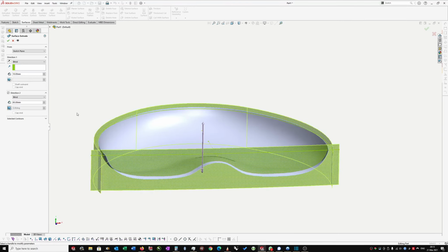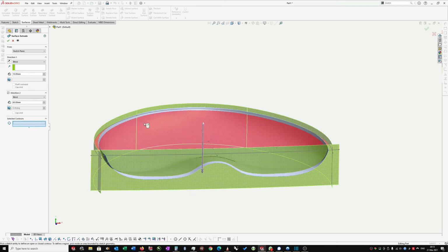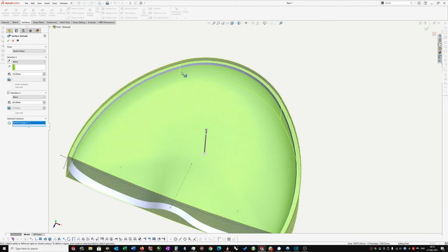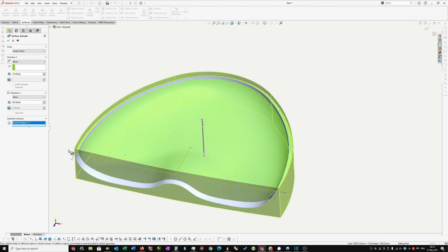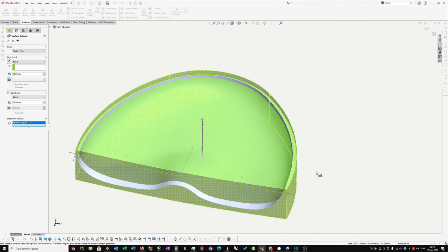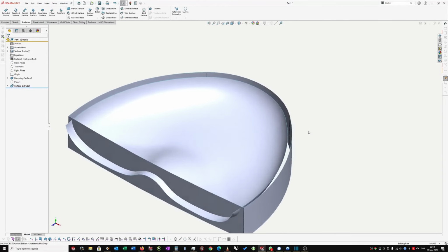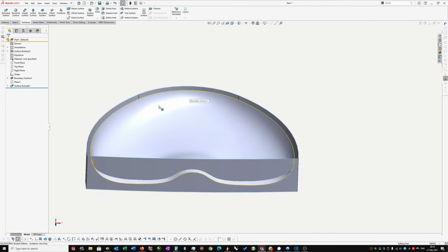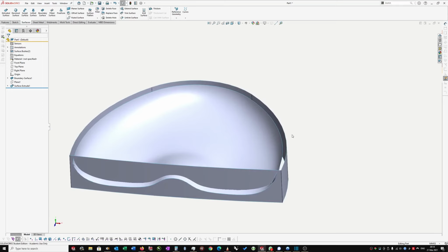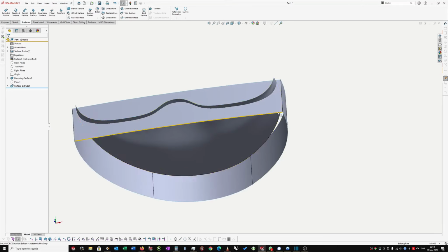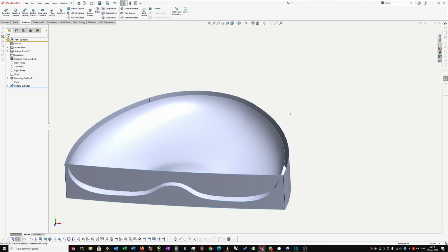So I don't want to do that because I'm going to assume you're just copying what the wood one looks like. And then I can go to the selected contours, and instead of selecting the sketch, I can select the region inside. So now, instead of giving us those extra bits and pieces, which I don't need now, I'll just grab the outer ones. Right, so there the outer walls are of our seat, and this sort of dished part on the inside. We just need to cap this bit and the base, and then trim everything.